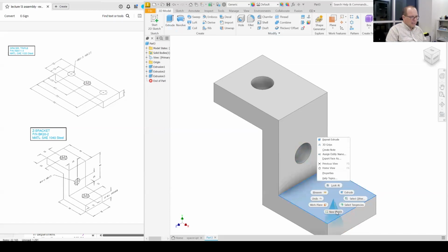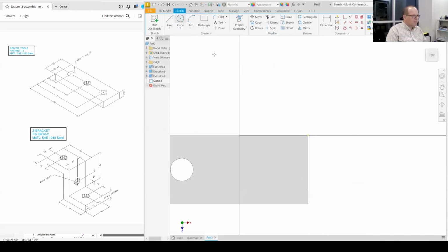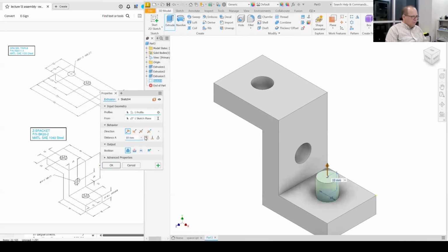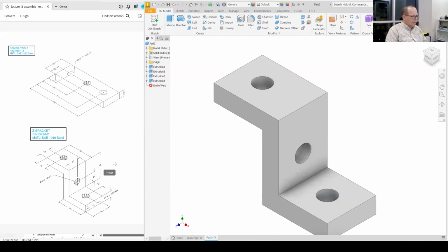And then the last one. Halfway there, and another 15 in, I'm assuming. And here is 30, yeah, so 15. This should be 15, 15, and 10. And again, we'll extrude all the way through. And there we go.